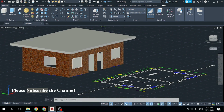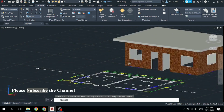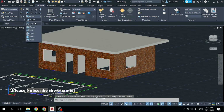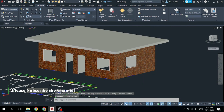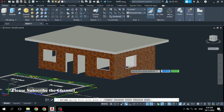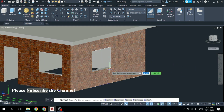To create 3D windows come to visualize and click it, and select this coordinate. So now I would like to create for this side, so it should be, let's show that side. It should be in a left, so select a left view. You can see this left, and after that come to home and take this rectangle command. You know that the size of this window is 5 feet by 4 feet height, and 5 feet